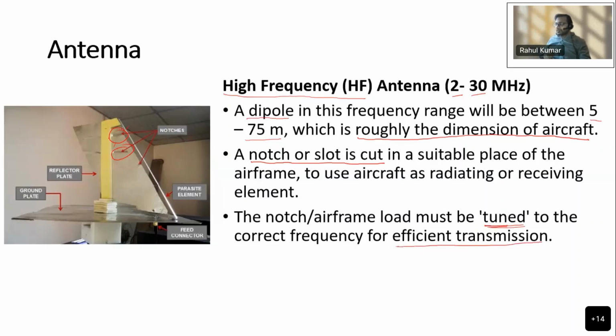Okay, so without tuning, very little energy will be radiated, and you will have a large value of standing wave. So with standing waves, you can say they stand, they do not radiate. If you do not design it properly, you will have more standing wave and less radiation from the notches.